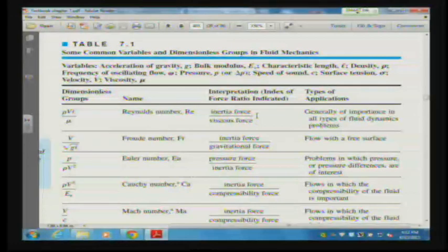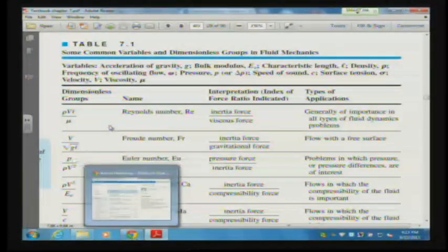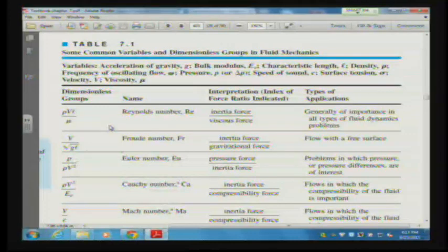Now, this is a number that very often when you see an airplane, a prototype, not even a prototype, but a model in a wind tunnel, the model will not look all that similar to the plane itself. And this is the case of the picture that I've put on our Moodle page. You'll see that we sort of have a distorted airplane prior to its being tested in a wind tunnel. The reason is because we need to have the similarity of a Reynolds number, and in order to get that to happen, it's going to look geometrically a little different.